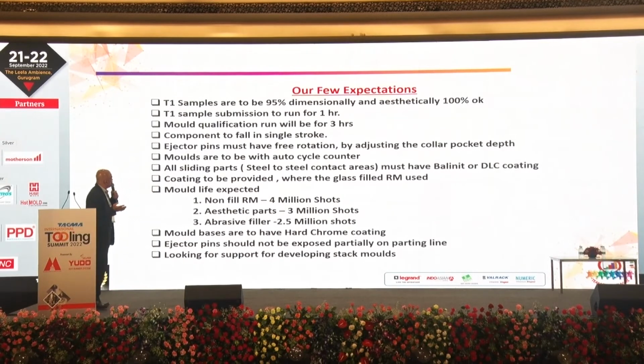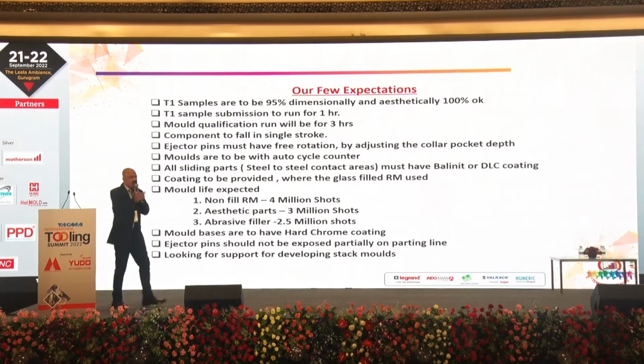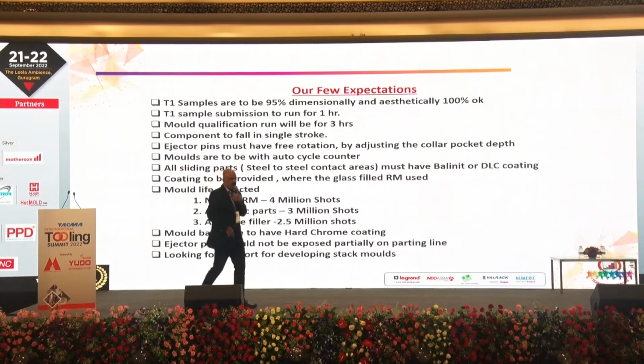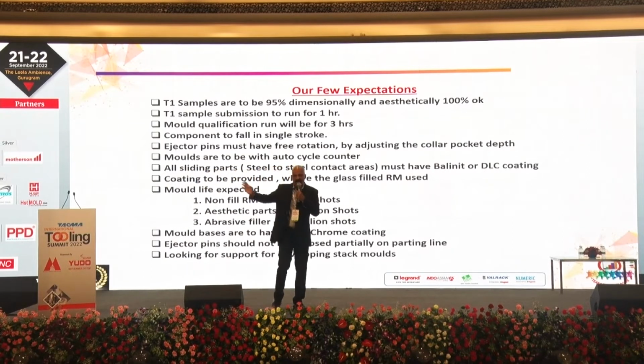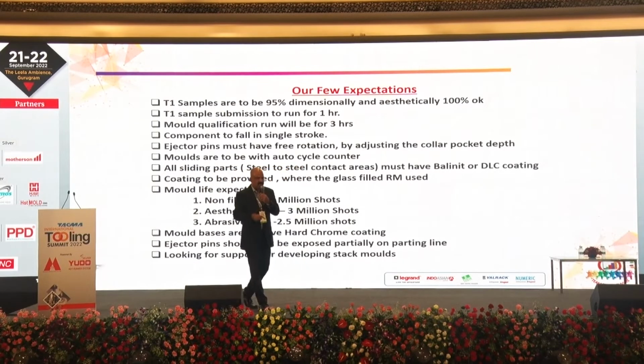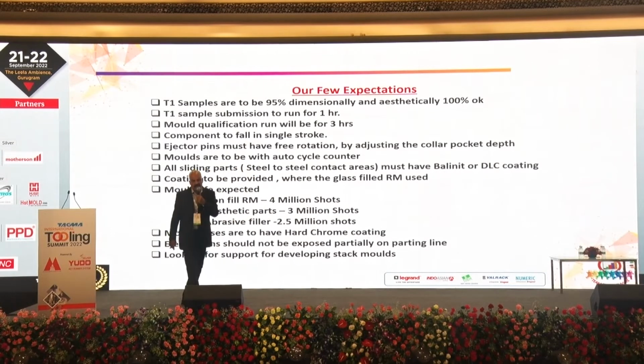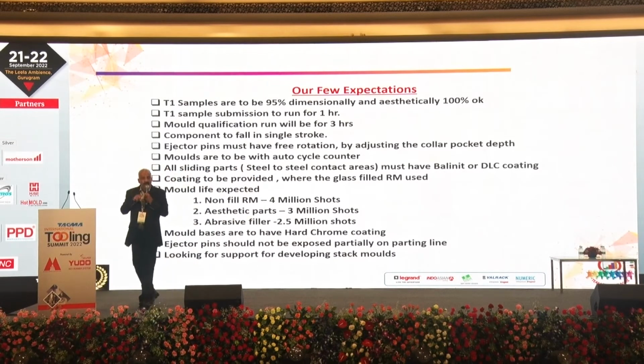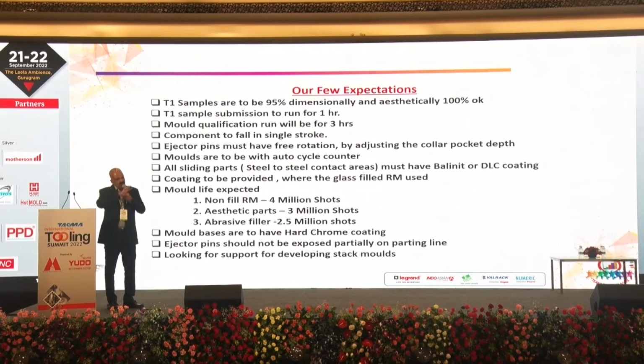First, T1 sample submission: run for 1 hour. Not that the mold is ready, take 10 components, come by the next flight, and give them to R&D. No, run, stabilize the process, and then give the components to R&D. So you will not get the surprise of the buy-off trial. Your mold is already established.